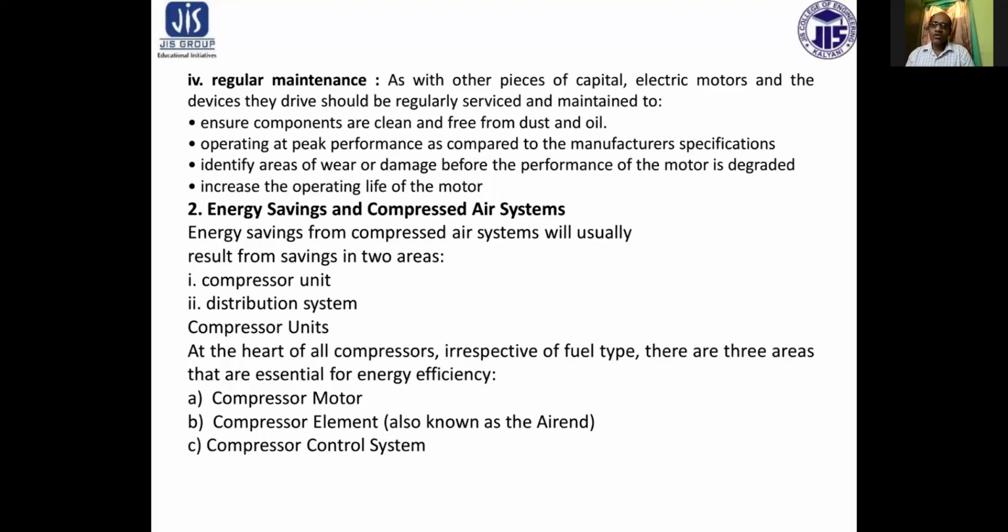And last of all, the compressor control system. The development of the microprocessor has had an important effect on the efficiency of the compressor. Modern controls are able to match the air supply to the demand much more efficiently than is possible manually, and savings of up to 45% may be possible through the installation of a number of smaller compressors which can be brought on automatically to match the demand for air.